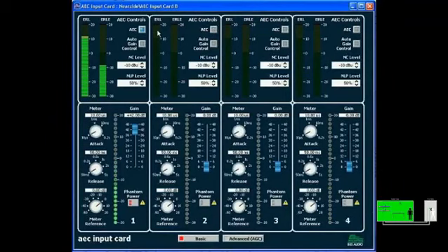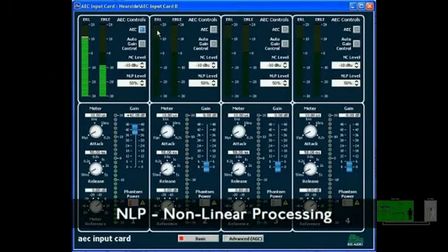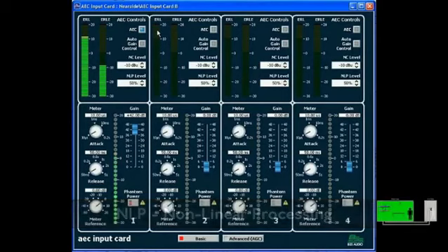Now let's talk a little bit about nonlinear processing. Nonlinear processing, NLP, is used to eliminate the secondary, indirect type of echo or reverb that is caused by the acoustic reflections in the near side room. Traditionally, the NLP level must be carefully tweaked until achieving a delicate balance between best double talk performance at 0% and best elimination of indirect room-colored echo at 100%. The specific NLP level at which these two performance factors are optimized is often referred to as the sweet spot.